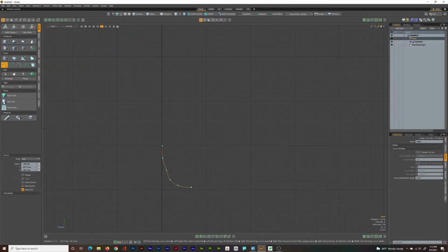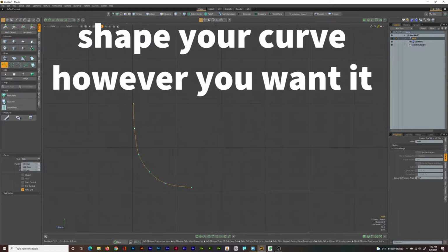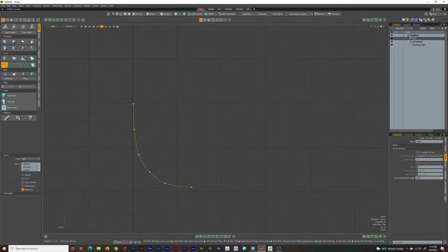If you hold Control and the space bar at the same time, you have access to all the different views, like right view, left view, top, back, or perspective view. At this point, all you've got to do is drag the curve out and straighten it out to your liking. Now there are other curve options within this program that could make this part a little easier, but right now I'm just working with the base curve tool.